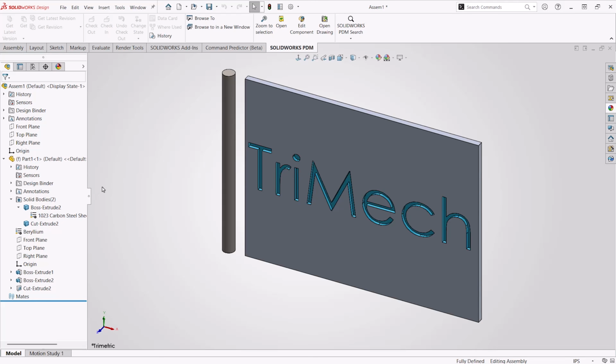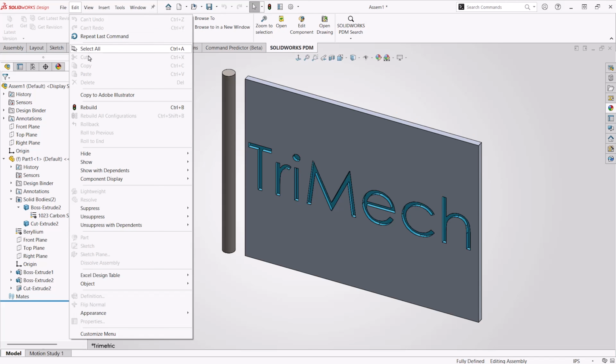And again, we can go to the edit, appearances, and material selection here, but in an assembly, you must have something pre-selected in order for this to appear as a selection that is enabled.